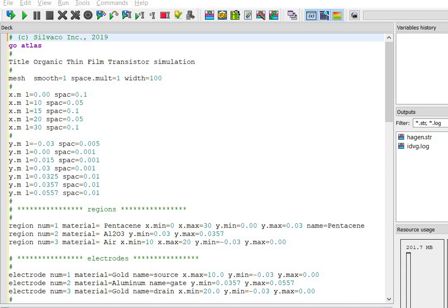After defining the structure layers with the appropriate dimensions and material, individual simulation domains are divided into finite element grids, that is called meshing, that comprise a complex grid of triangles. At these discrete grid points, the model entails the calculation based on elemental device physics equations related to electric field, electric potential, and charge carrier density.